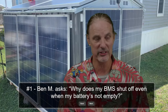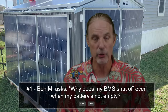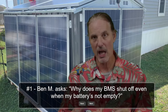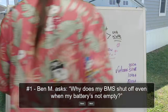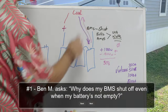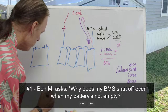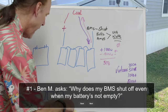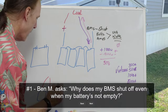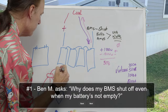So my suggestion in this case for Ben is to take the Victron shunt and put it in line of your system. And let me explain what I mean by that. We'll go back to the whiteboard over here. So when your battery is feeding this energy in and out, and let's just assume that this could be a battery bank and you have multiple batteries down here, I would suggest that you take multiple batteries and run them to a battery bus and you run your load off of this.